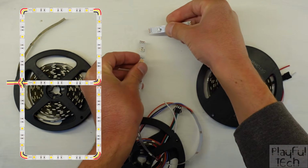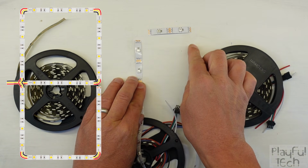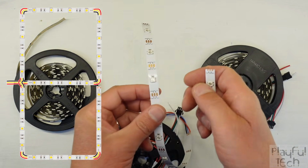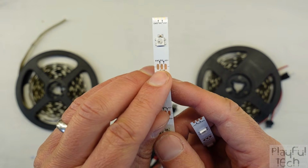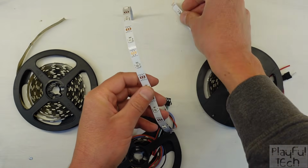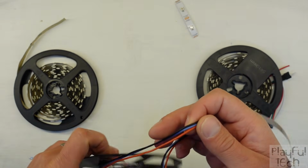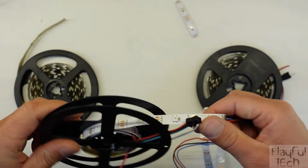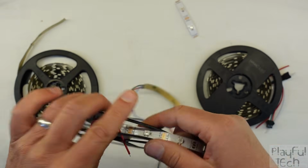And what you can do is cut several of these strips and then lay them out into the shape of a 7-segment display, then solder wires between those cut copper contacts on the corners. One thing to mention is that the strip does have a direction, which is indicated by the arrow here. So there's a data in to each LED, and then there's a data out that goes to the next one in the strip. So if I unravel the whole strip, we can actually trace it right back to the start.